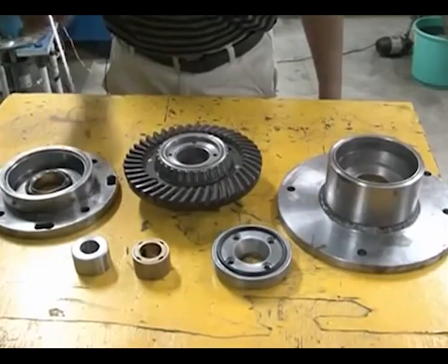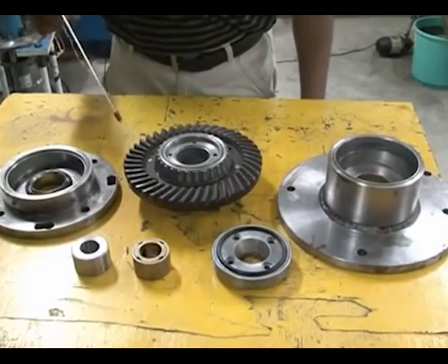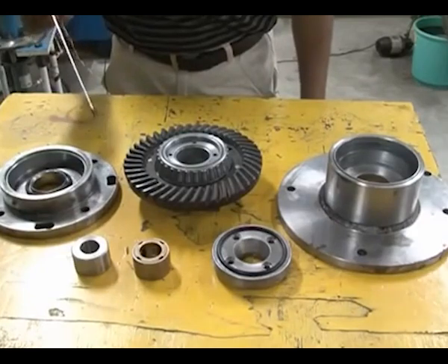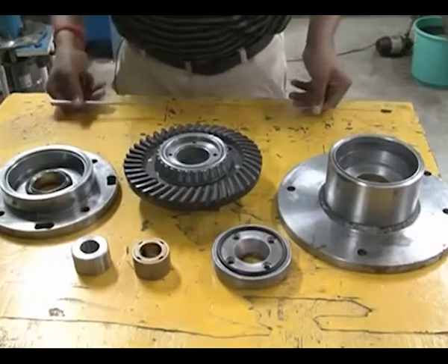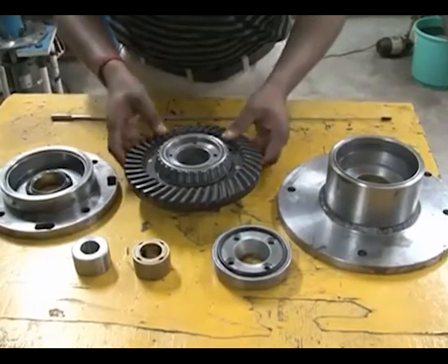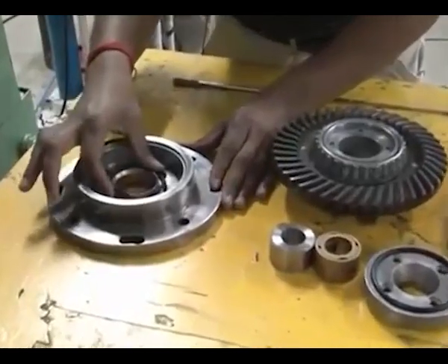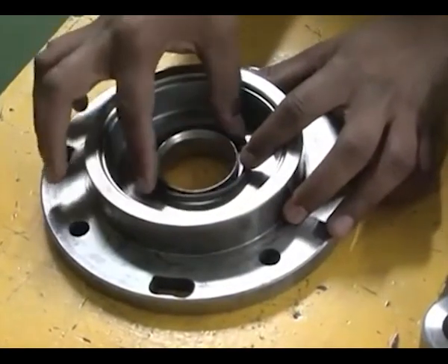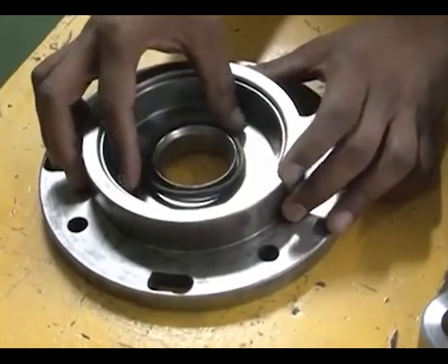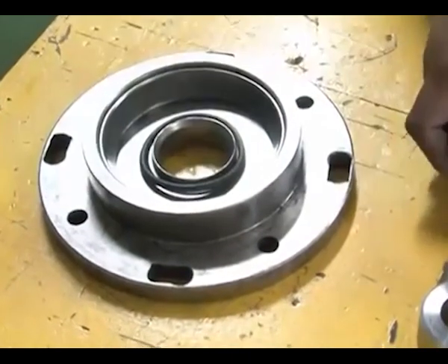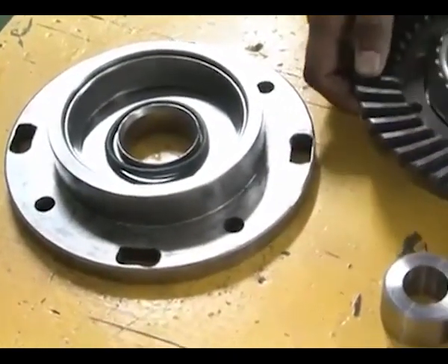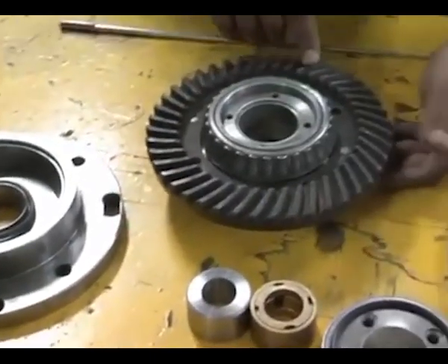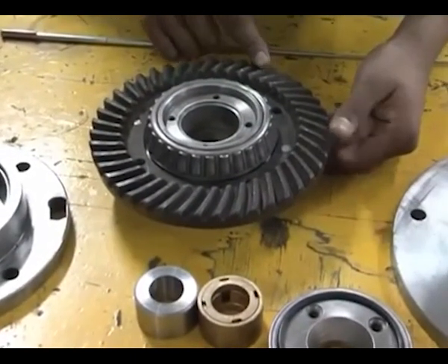Now you are seeing the rotational tooling that we are using in the universal rotational abrasive flow finishing process. The inner details are as follows. This is the bottom plate, wherein we have a curved surface where we place the O-ring to prevent leaks, and this is the crown that is made specially for the rotational system.